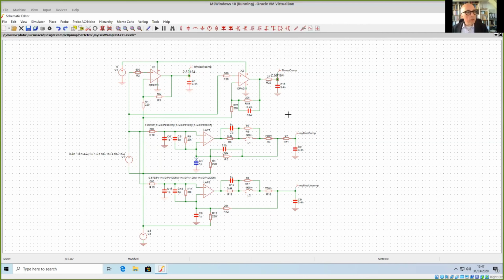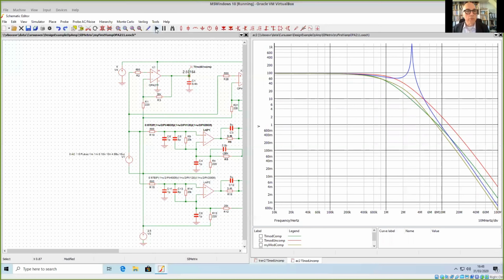And here is the compensated circuit. So here you have the phantom zero compensation, 2.2p and 727 ohm. And here you have the same without simulation. And now the question is, what does it show? Is it reliable if you compare it to the measurements? Because the measurement is Mother Nature, and Mother Nature is always right. So you see, this is really a fast simulator.